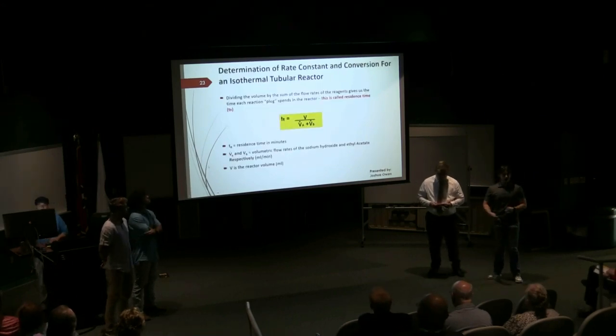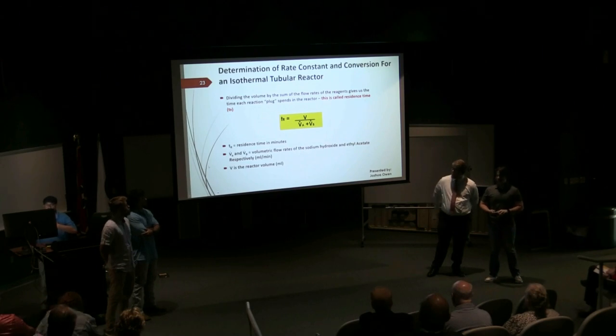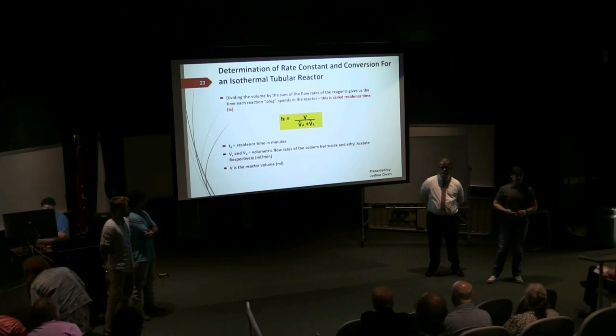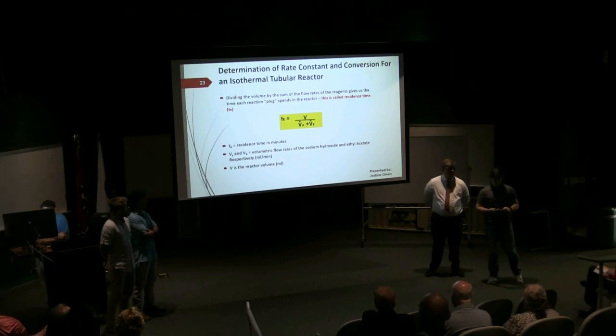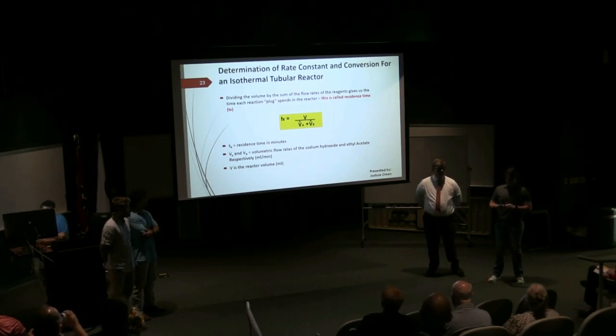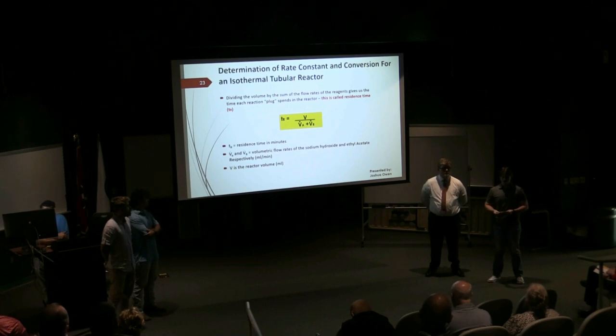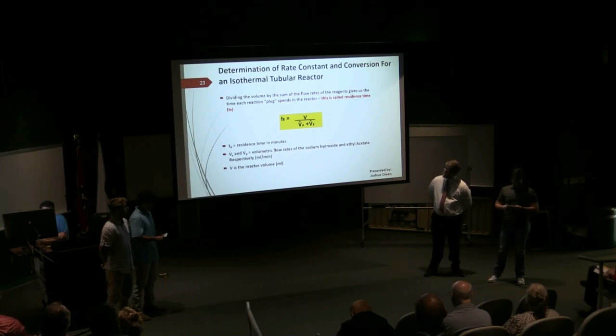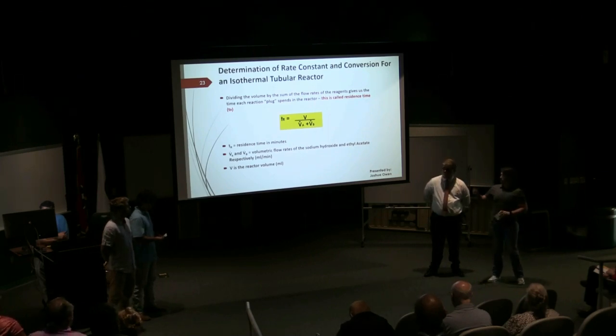We studied 2 types of reactors, which were a batch reactor and a plug flow reactor. We need to go over some terminology for the plug flow reactor. Residence time is how long a reaction plug will stay in the plug flow reactor, and that's determined by taking the volume of the reactor and dividing it by the volumetric flow rates of both A and B.